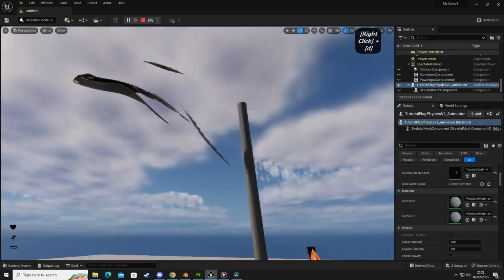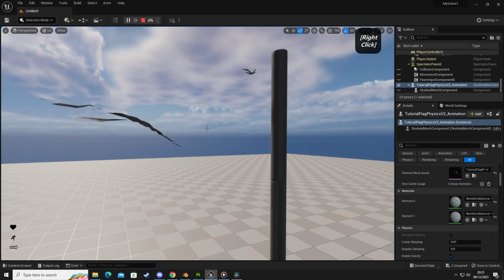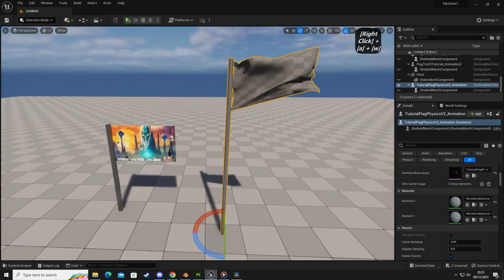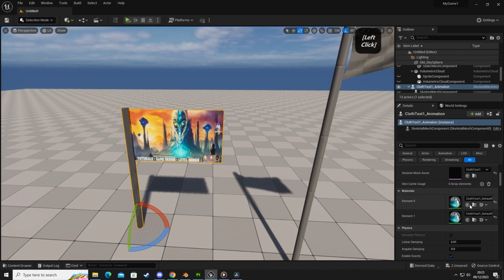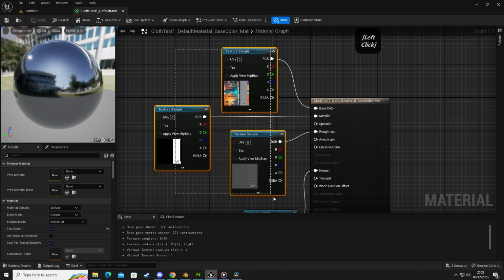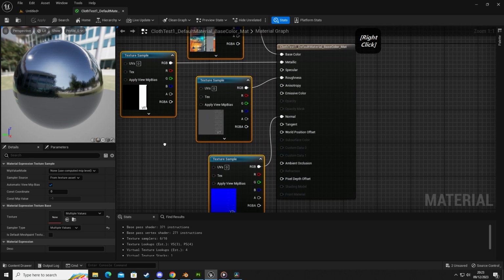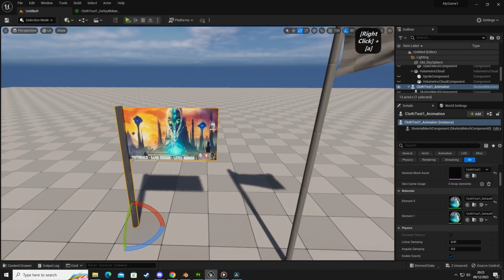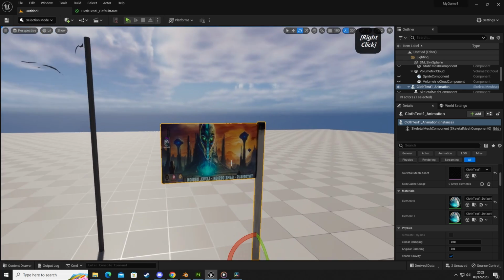A quick reminder that it has only got normals on one side, which is not a problem. All you have to do is make sure that you set your material. So in your material properties for your object, when you bring in your material file, you need to make sure that when you select your material, you check on two-sided, and this will draw the texture on both sides.